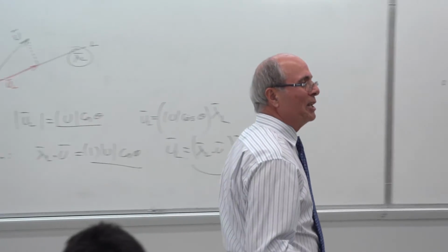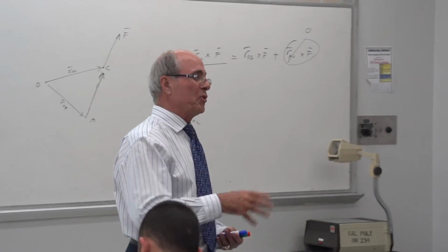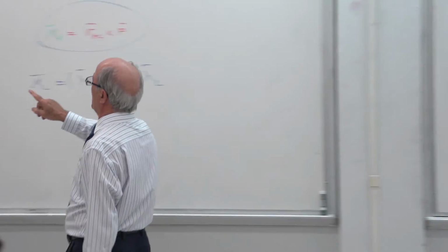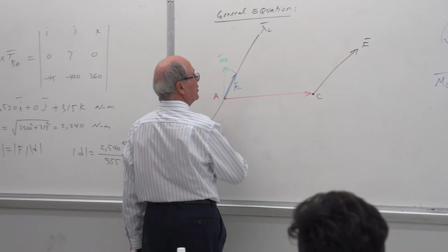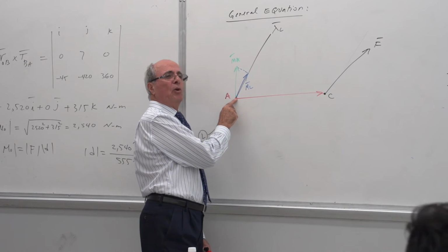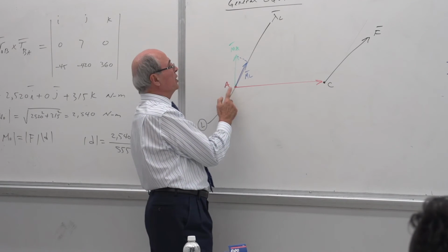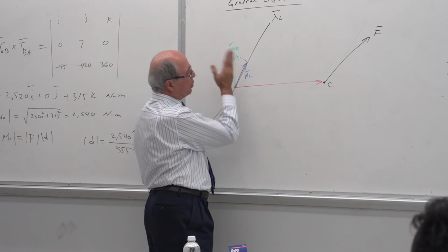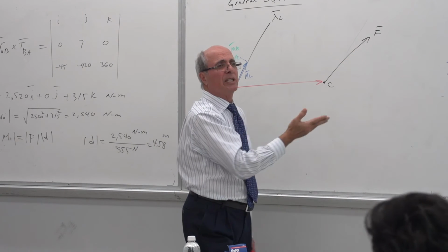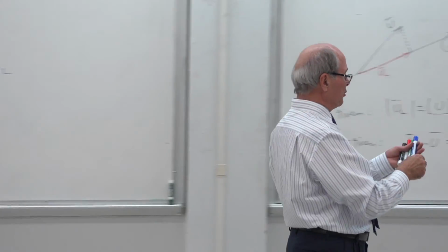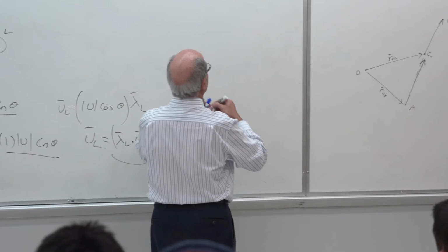That is what I was doing before you realized it. This is the definition of moment one more time. Finding the moment of F about this line is this. First you pick a point on the line. Take the moment of F about that point, which is this green vector. Then project it by that law over the line, and that's your moment. Is that correct or not? That's exactly what I did without you realizing.